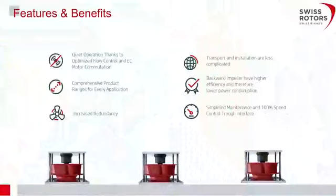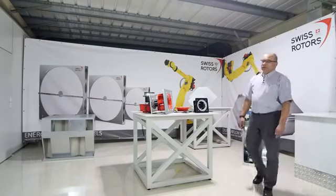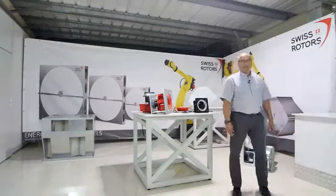Then we can have some increased redundancy. For example, if one motor fails, and there were 6 motors used in the array, then the other 5 motors can slightly increase the RPM by the controller and keep the air volume on the same level. You just need to close the suction side of this non-working fan, and then everything will be fine. And then you have time to change the impeller, and of course the exchange is much easier, because